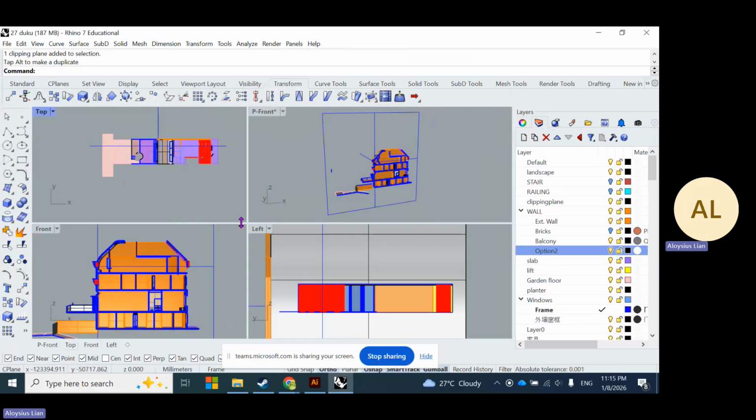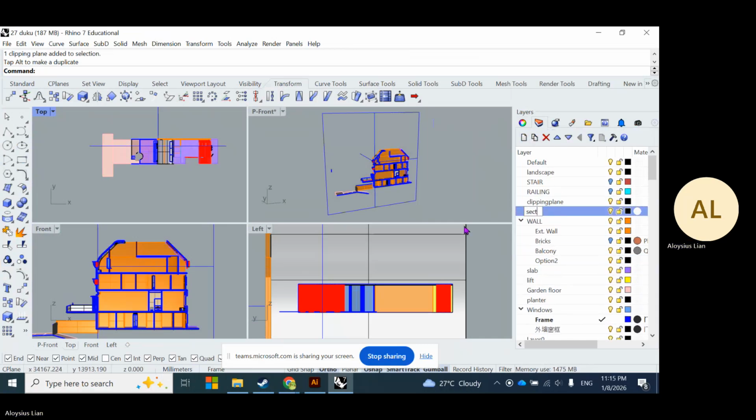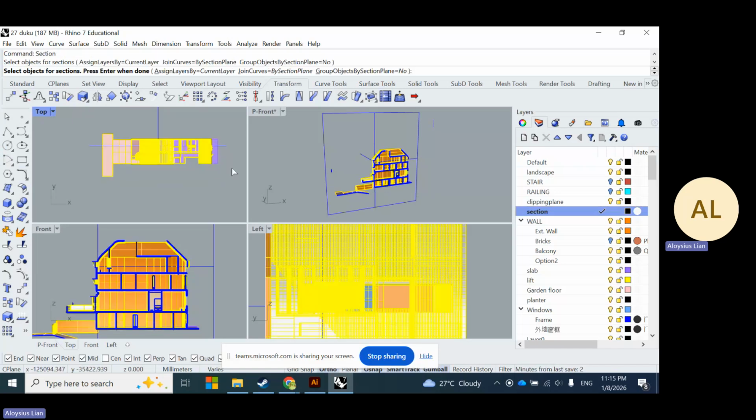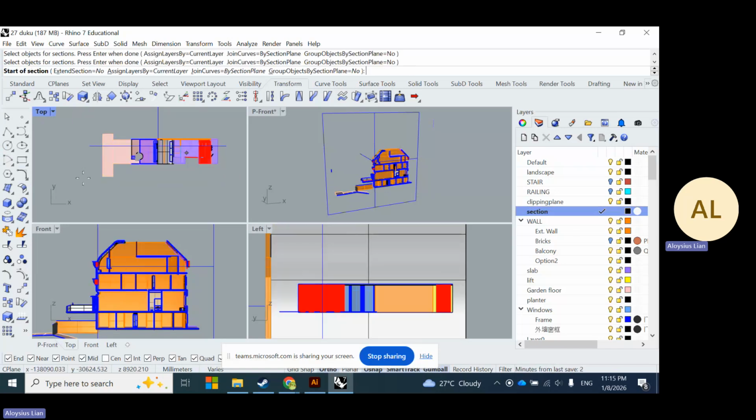type, create a section tool also. Section, make this active, type section. So objects to make section of will be your stuff here, as well as here, enter. So start here, and end here, and enter.